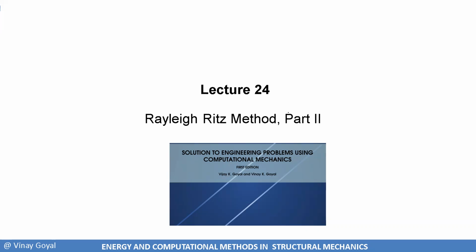From there, I moved on and said, okay, what if I use an idea based on calculus of variations, and consider now the principle of virtual work, where the internal virtual work equals the external virtual work. And that's the most general framework you can ever have for structural mechanics. When I applied that to a 3D problem, I found that the Euler-Lagrange equations miraculously were in fact the stress equilibrium equations with the Cauchy's relationships as the boundary condition. That was quite exciting actually.